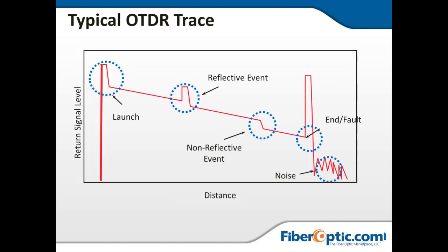We're not sure, not by looking at one wavelength, which again we have here. I'd like to see this maybe having two wavelengths in here, so two traces kind of overlapping each other, because that's where we really get to see the 1310 compared to the 1550 wavelength, or the 850 compared to the 1300 wavelength, and be able to determine this non-reflective event. Is that a bad splice or is that a macro bend? Based on the information here, I really can't tell you until I had a little bit more information to be able to diagnose that, and that would be that second trace file.